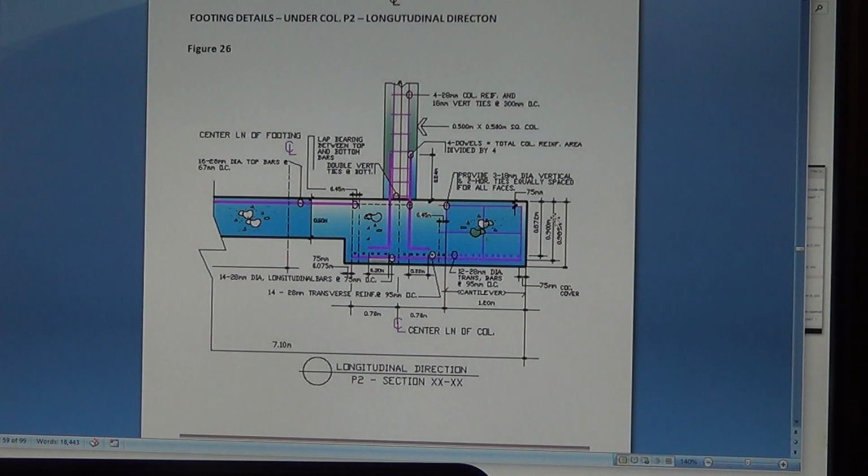According to the code, in the design of a beam, which is the same as the footing, when the beam is from 24 up to 36 inches, that is 2 to 3 feet, you have to provide web reinforcement in between. When you have that depth, 24 to 36 inches, the foundation will be provided with stirrups.